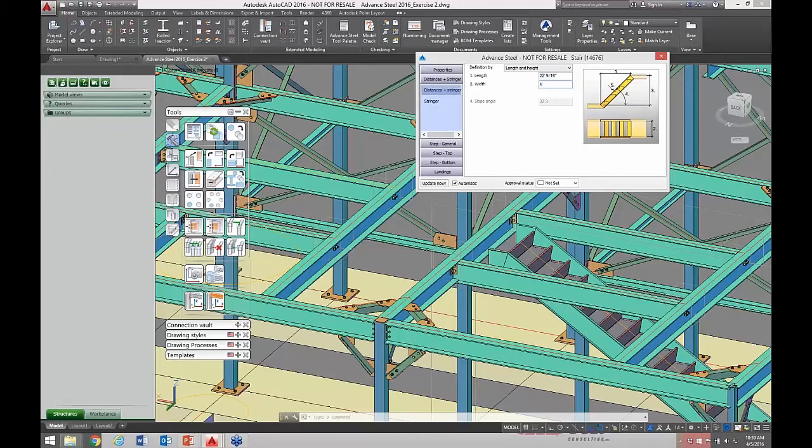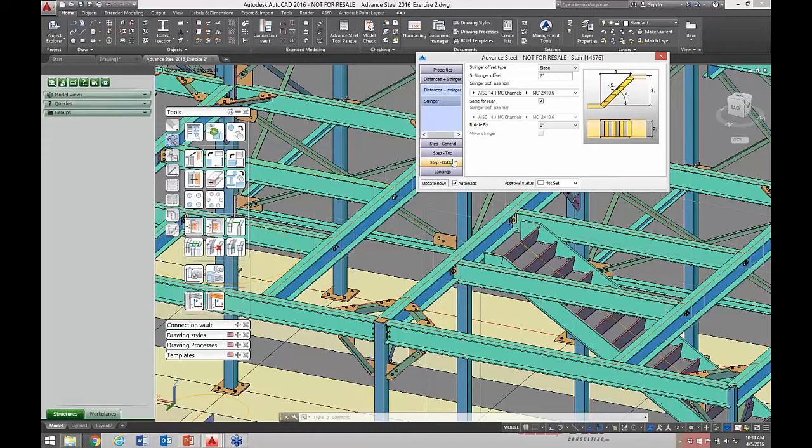And I can leave always the macro open. If that 4-foot stair fits between our two floor members here, then fine. But I can change width. The other values are filled in by the method of pick placement that I had defined. If I needed a different channel stringer section or another type, whether it's a solid plate or bar, or if I need a different size channel or a rectangular tube, whatever it may be, I can define my sections for my library.